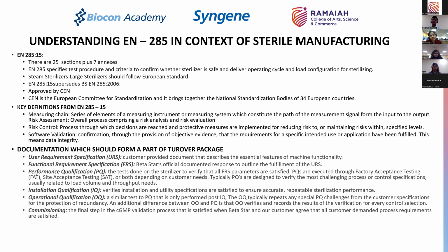If you want, I can show you this URS. An autoclave URS could go into a 50-page document itself, which goes on to specify the material of construction, the features I want, and the alarms that I want in the autoclave for my own process, from a process perspective and a machine safety perspective. A URS is the first document required as a part of your qualification of an autoclave.